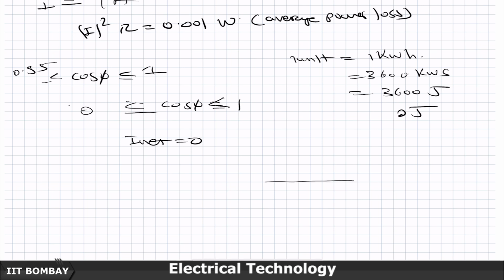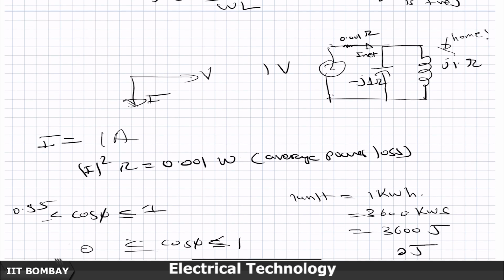The I net being 0, why is that happening? Because this is the voltage, this is the IL, and equal and opposite is IC. So the energy exchange now is in steady state, the energy exchange just happens between inductor and capacitor, with nothing being any further pulled from the supply. So they just play this game of power exchange. They are playing that game, no doubt.